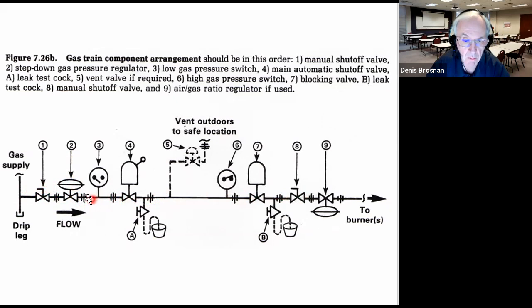What it actually is doing is functioning as a valve to let more or less gas into the system to create a constant dynamic pressure, meaning flowing pressure of gas in the piping systems that you have feeding the burners.